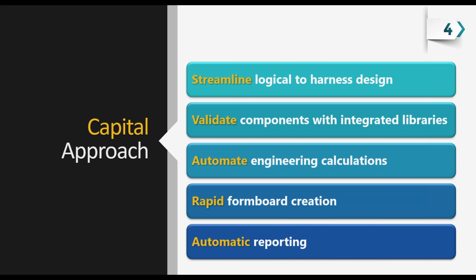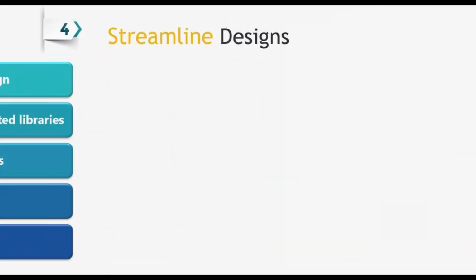Like in my previous life, instead of using marked up customer prints, create a one-to-one harness print that operators can build on. Finally, in order to get build data down to the production floor, automatically generate all of the manufacturing reports like BOMs, wire cut lists, installation lists, etc.